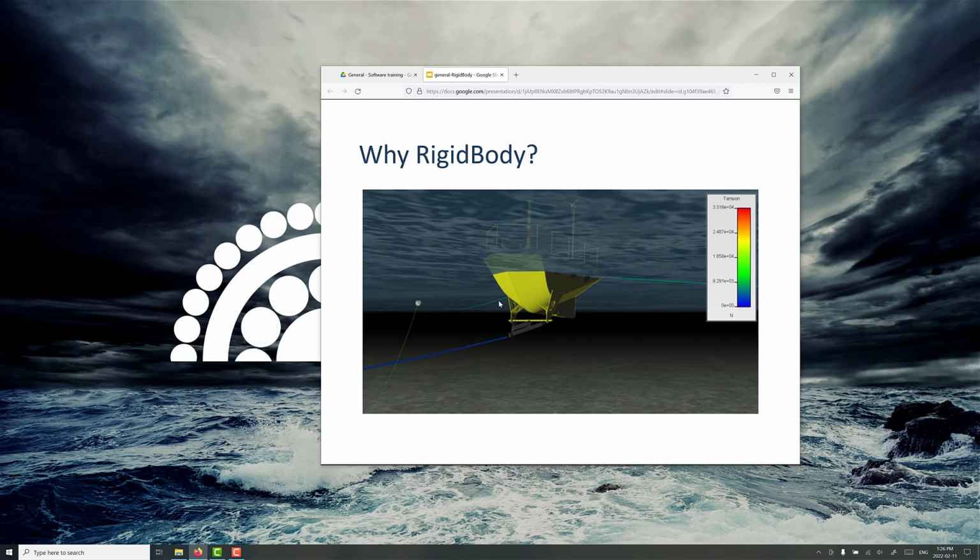And it's quite sizable as well, but because of its shape, it's nice to be able to use a lot of custom features here to allow the definition of the hull to play into the hydrodynamic loading. In addition, because they're bigger, often a lot more detail is needed in the orientation of how the pitch and roll of the buoy changes through the course of a simulation. And that's what the rigid body model is good for.